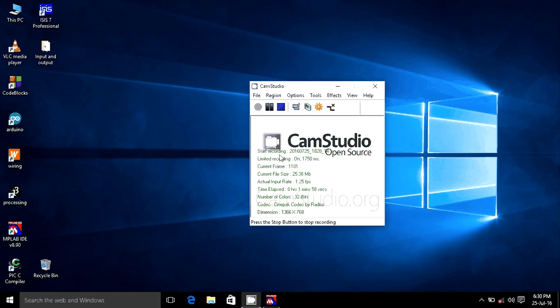The LM35 is a temperature sensor. This temperature sensor works with 0 to 5 volts. So we provide 0 to 5 volts to the sensor, and another pin is an output pin. We can use that pin as the input to our microcontroller on an analog port, analog pin, analog channel.